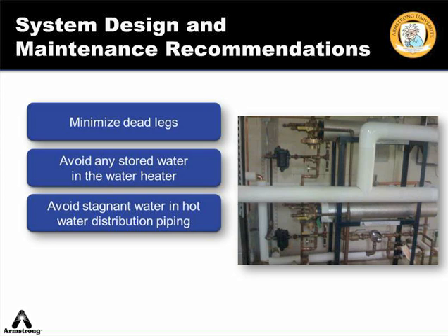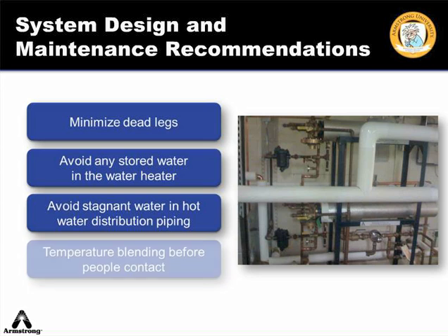Keep recirculation pumps running and well maintained. Recirculation pumps should also be excluded from energy conservation measures. It's critical to keep water circulating and turbulent to reduce the risk of Legionella colonization. Water for people washing heated in the loop to prevent Legionella cannot be used at that temperature directly by consumers. It would need to be blended down to a safe user temperature.